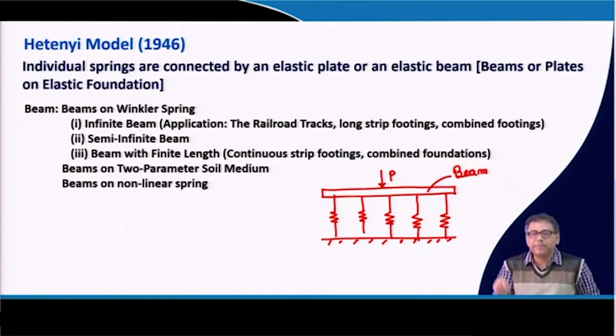Now again, nonlinearity, time dependent effect, all this can be incorporated. Now the question is, as I mentioned, that settlement cannot be confined within the loaded region. But if this beam is resting on a spring only, then again the settlement will be confined within the loaded region. But if you want to get the settlement beyond the loaded region, which is the actual case, then you have to place this beam on a 2-parameter model. So that means this is the beam on Winkler model or Winkler spring.